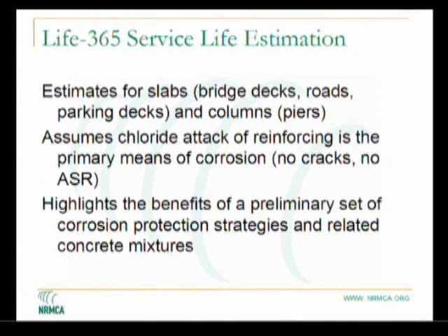The primary mechanism of corrosion in Life 365 is still chloride attack. In other words, it does not address cracks, it does not address ASR and some of the other means of attack. And the reason for this is that this is a difficult process from a research standpoint, a laboratory testing process, trying to accurately capture those effects into equations that can be run in software and a methodology is still a difficult process.